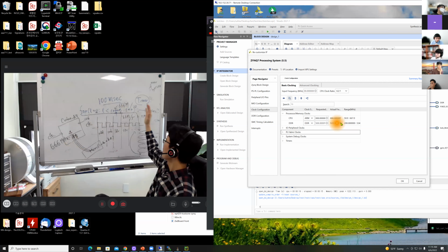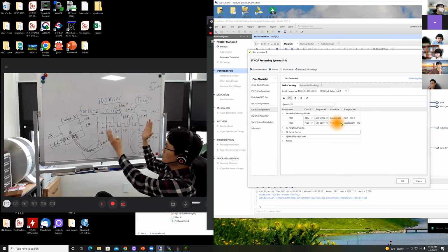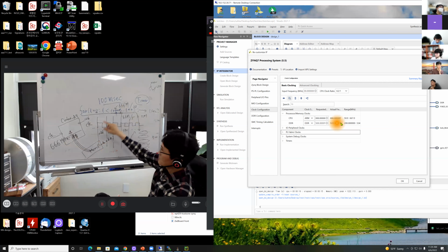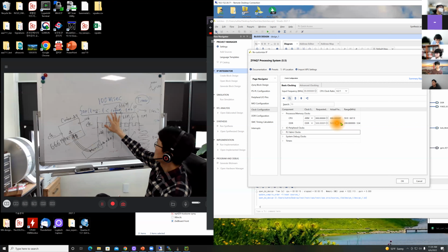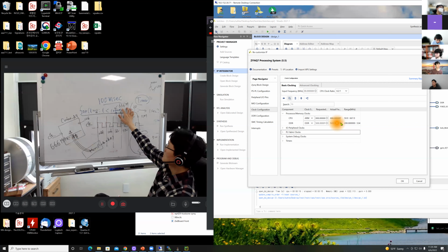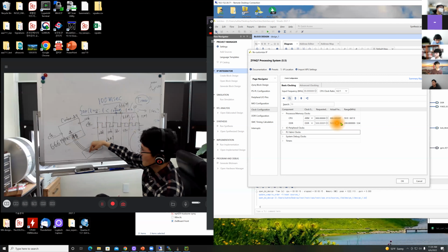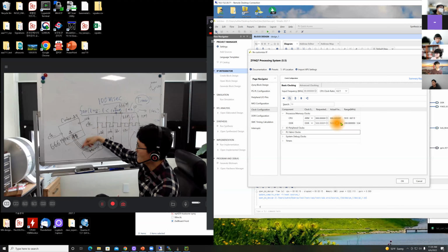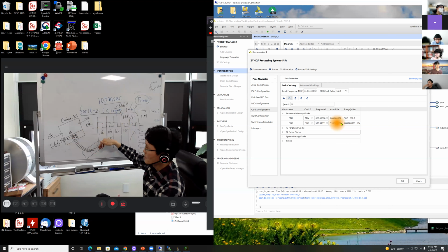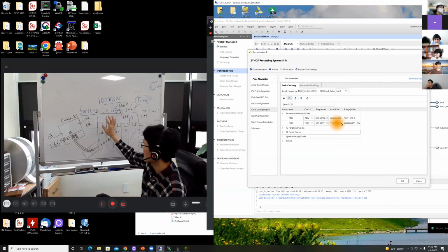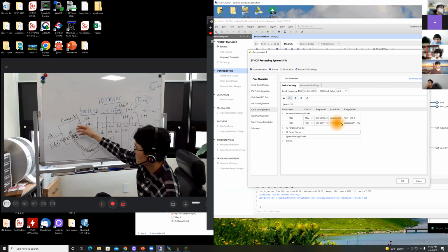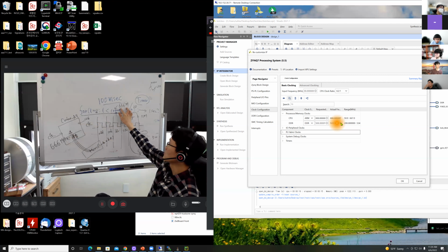So to create a 1 second interval, 1 second duration, probably that is a number you want to play with first. But you want to reduce the number, okay? Because of main memory access time, it takes more than 10 clock cycles. In a desktop computer system, it takes more than 100 clock cycles to get instruction or data. So you want to divide the number by 100 in a desktop system.